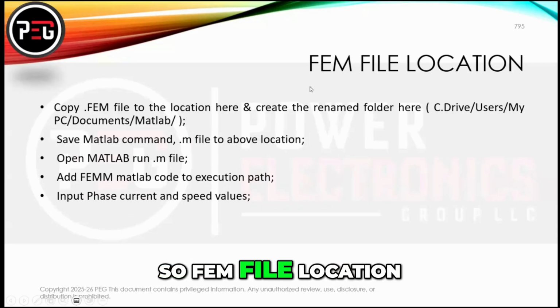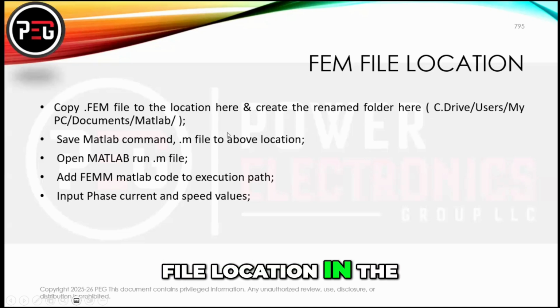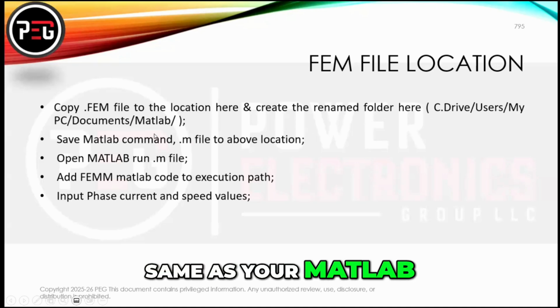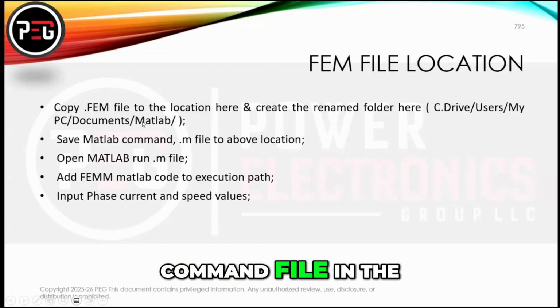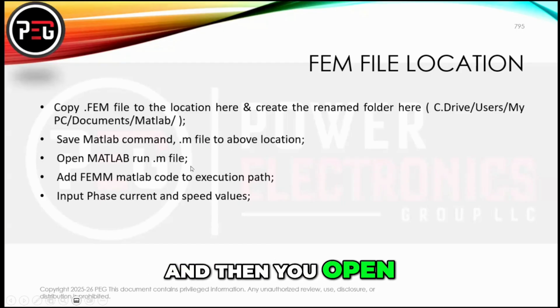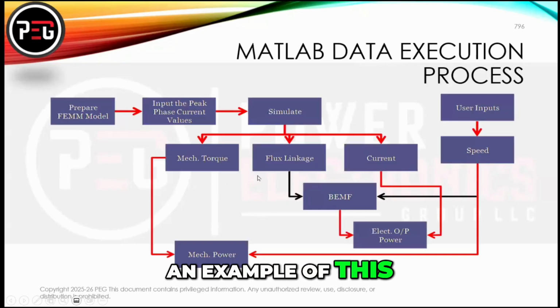Okay, so FEMM file location, you want to put your FEMM file in the same location as your MATLAB folder under your documents, and then your MATLAB command file in the above location, and then you open your MATLAB file, and then you add your FEMM MATLAB code execution path, and then input phase current and speed values. So we'll go through an example of this, okay?